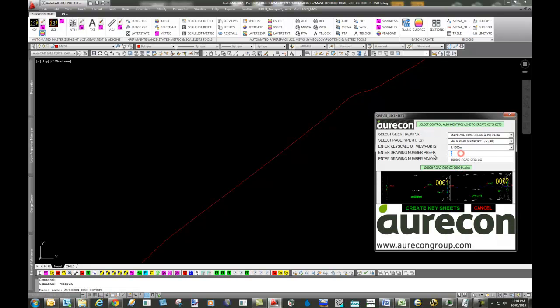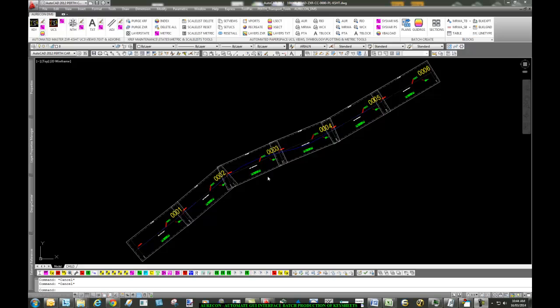The drawing prefix, we'll just set it to 0. It's basically for the series when you're doing interchanges and multiple alignments in transportation. 9 times out of 10 it will just be 0. And the type of drawing that we're linking, so if you look up the top, 1000 road ZXR, so we're going to need 1000 road drawing with the discipline CC. Okay, so we've got an option here to...